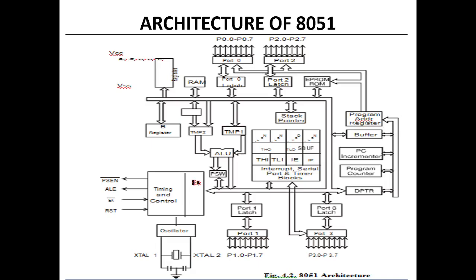In this architecture, the Intel 8051 contains two separate buses for both the programs and data. So there are two distinctive memory spaces, 64K by 8 size, for both programs and data. That means the RAM has 128 bytes of memory. It's based on an 8-bit central processing unit with an 8-bit accumulator and another 8-bit B register as the main processing blocks. Other portions of the architecture include a few 8-bit and 16-bit registers and 8-bit memory locations.